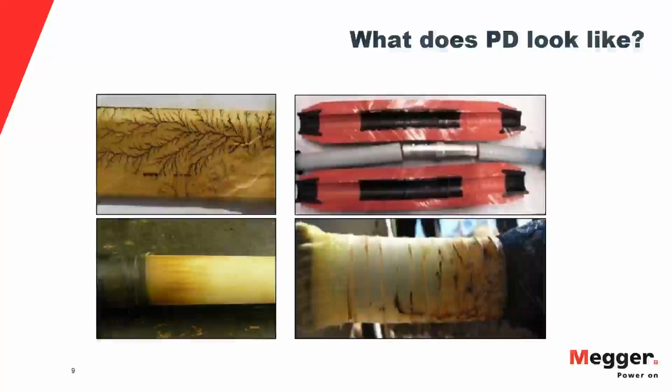What we see here on this slide is incomplete shrinking, where this whole area, if I can highlight it with the pen, that's all experiencing partial discharge because there's an air gap up here that wasn't completely shrunk. It's very common for the top of a heat shrink splice to be well treated, but the bottom is maybe a little bit harder to get to, and it might not be completely shrunk.